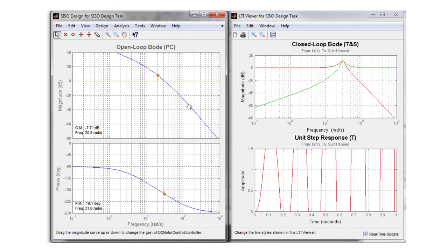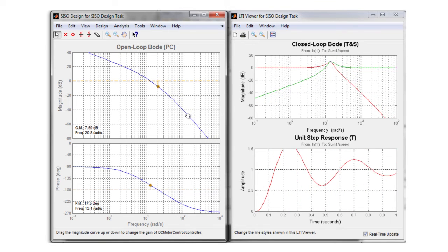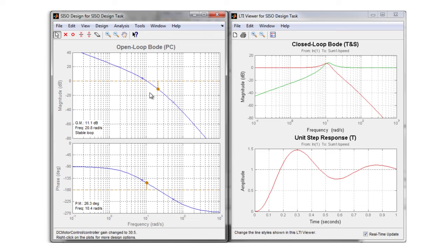So ideally, we want to pick a gain that gets us close to the system response speed we're looking for. Actually, I'm going to choose a crossover frequency of about 10 radians per second, which corresponds to approximately 0.15 seconds of rise time we want to target. But as you can see, it results in an unacceptable overshoot. So as we found out from the simple gain, a pure integrator alone will not be able to achieve the performance we need. What we need is better damping, which means additional phase margin over here where it's less than 30 degrees.